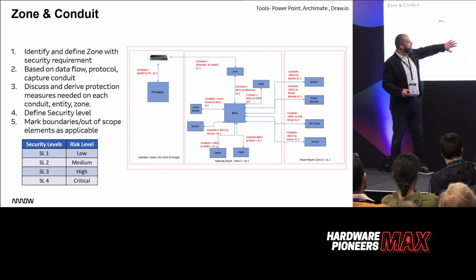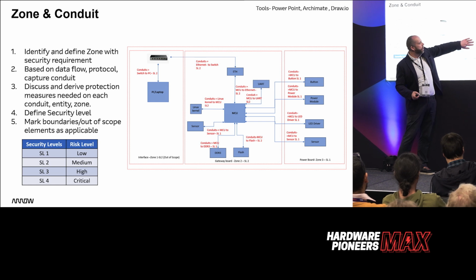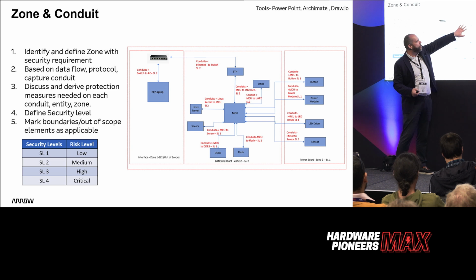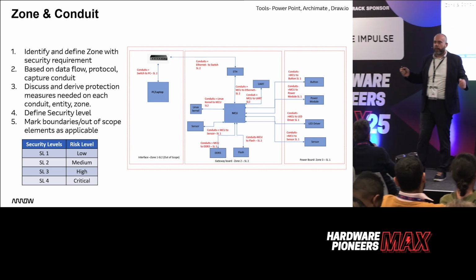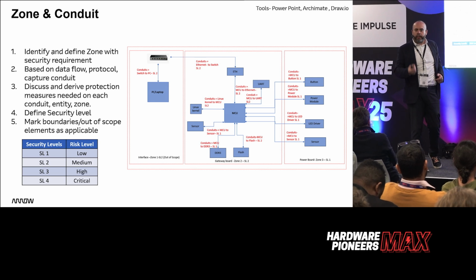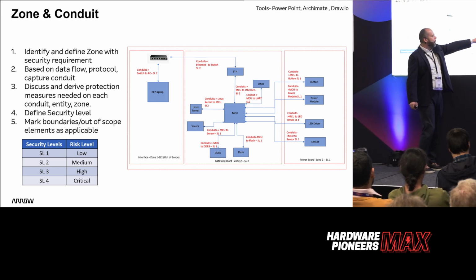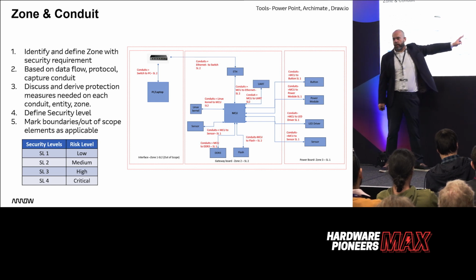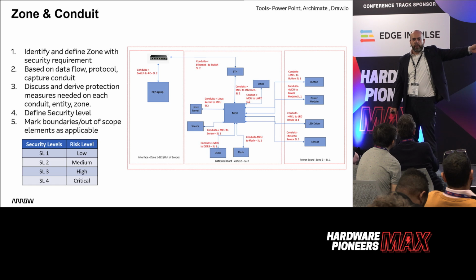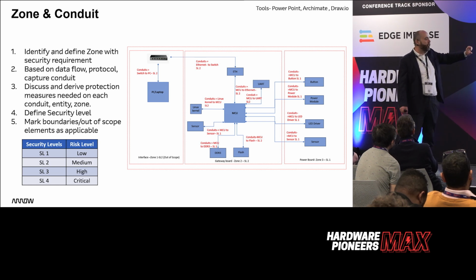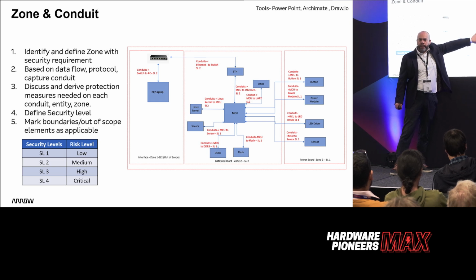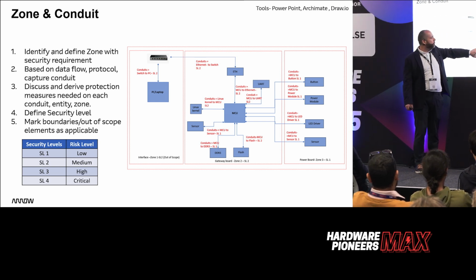And now the bits that we're interested in, and this is the bit that we kind of expect. You've got some form of processor. It talks to the internet. That is of interest, okay? That is what we think of with CRA. But like I was saying earlier, it's defined as connectivity, not internet connection. So a bog standard little UART, and if you're like me, you probably still design your UARTs with resistors so that whenever you realize you've got TX and RX the wrong way around, you can still swap it over because you never get it right. If you've only got UART connectivity, it's still a connected device. Okay.